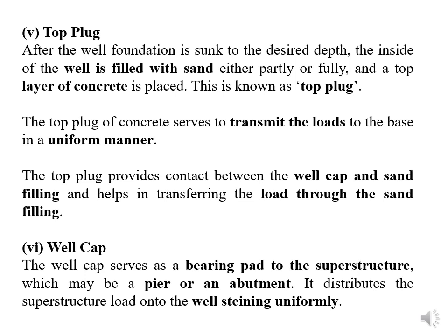What it does, you can see here, the well cap serves as a bearing pad to the superstructure, which may be a pier or an abutment. It distributes the superstructure load onto the well steining uniformly. Because the walls of the well, which is called steining, are going to take the load of the superstructure. So what is pier or abutment?